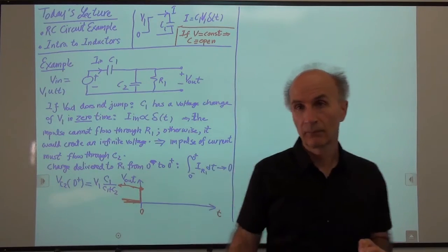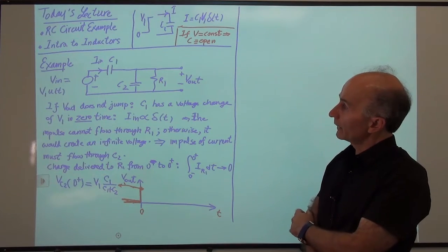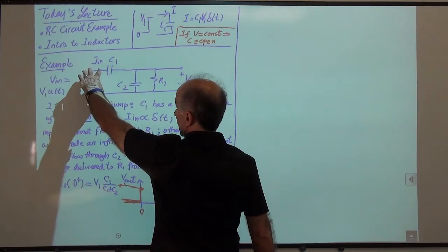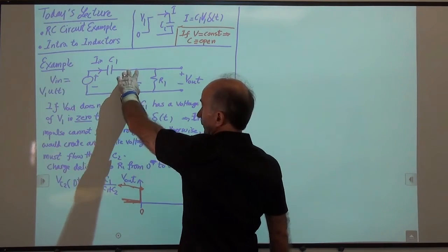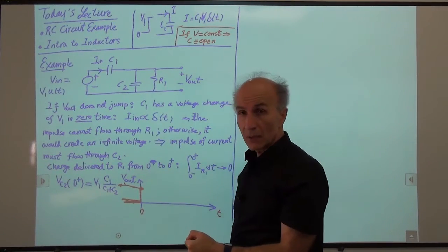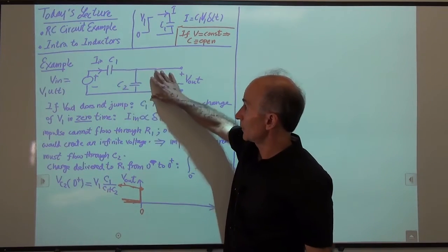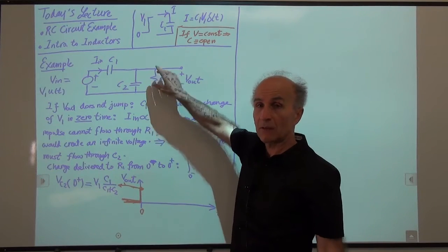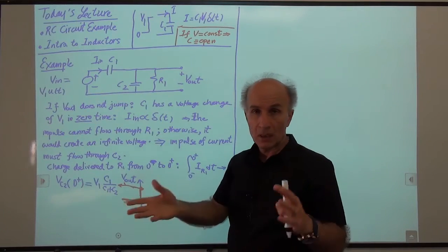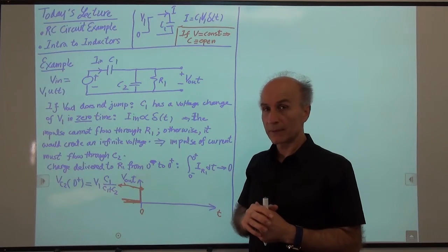Okay. All right, so we're going to look at the circuit a little while and understand exactly what will happen. This voltage is now V1. It's a step, right? It's like a battery, V1. This capacitor has some finite voltage on it, this much. And now we have this resistor. So our expectation is that this resistor will discharge these capacitors over time. It wants to draw some current, right? Any finite voltage here results in a finite current, so R1 begins to discharge these two. But we have to be careful here. So let's think about it as follows.